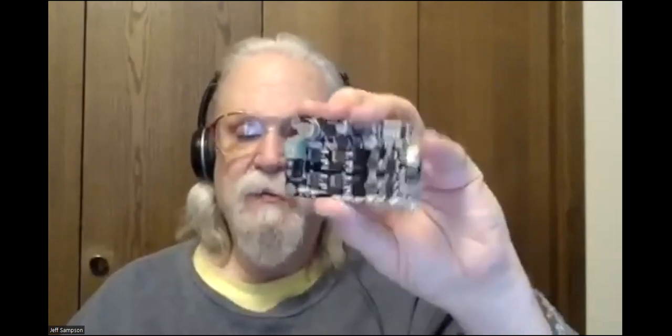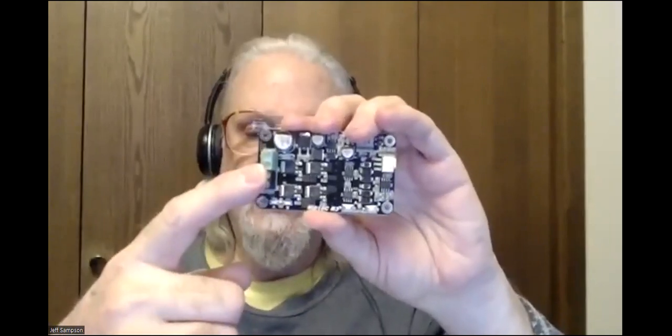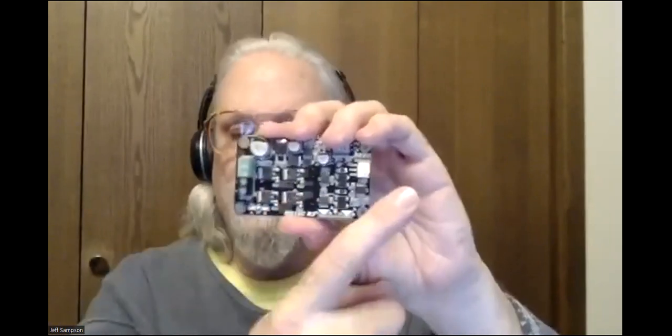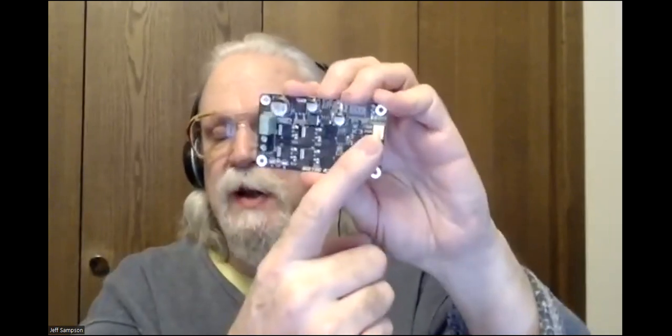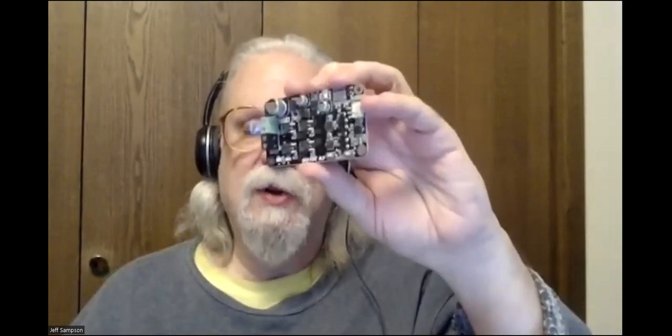So I just took an ohm meter here as the meeting started and checked. And sure enough, on one side, the ground pin here for the incoming power and the ground pin on the logic over here are connected together inside the board. So whatever Terry's problem was, it's still baffling. And someday we should track that down and figure out why. But anyway, I haven't had an issue with it, and I have not connected that ground back together. So you shouldn't have to connect those grounds together because they're connected on the board, which brings up problems later when we talk about noise problems.